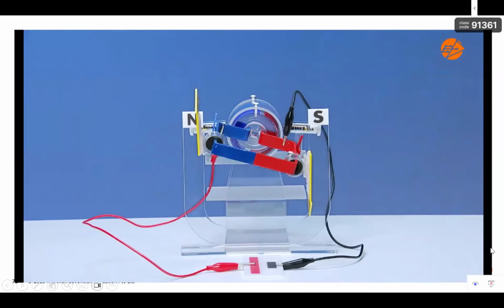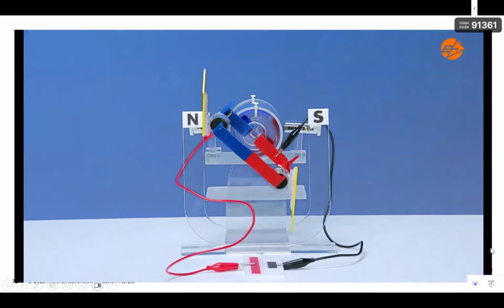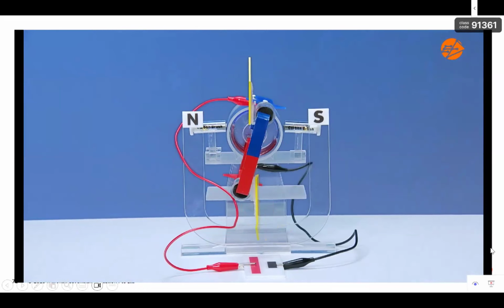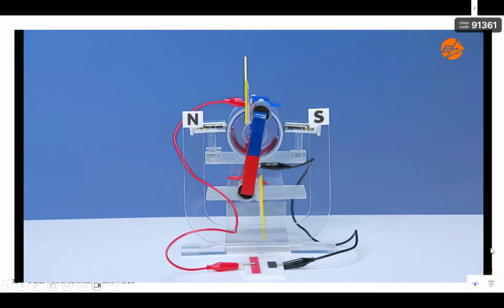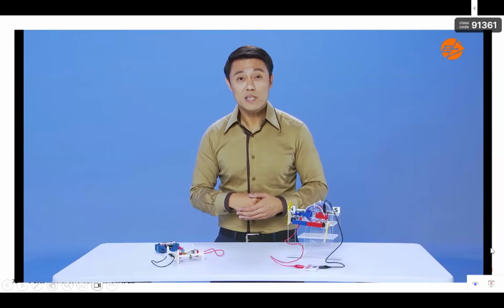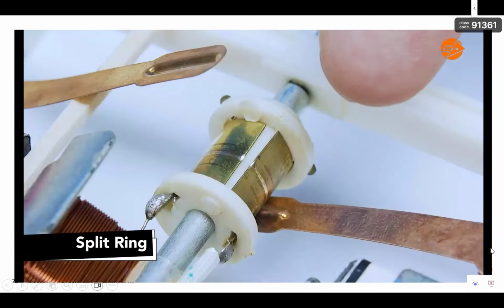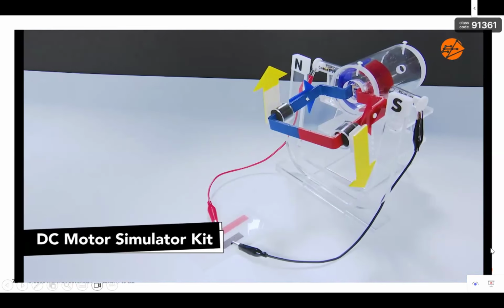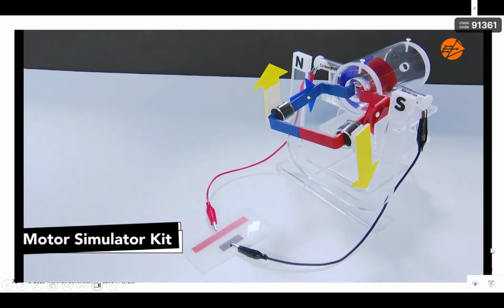At the coil's vertical position, the directions of the magnetic forces are acting vertically upwards and vertically downwards. As both equal forces act in opposite directions, no turning effect is created. As a result, the coil stops spinning. Now, let's observe our DC motor setup with the split ring. The DC motor setup spins continuously. We will refer to the DC motor simulator kit to understand how the split ring enables the continuous motion.